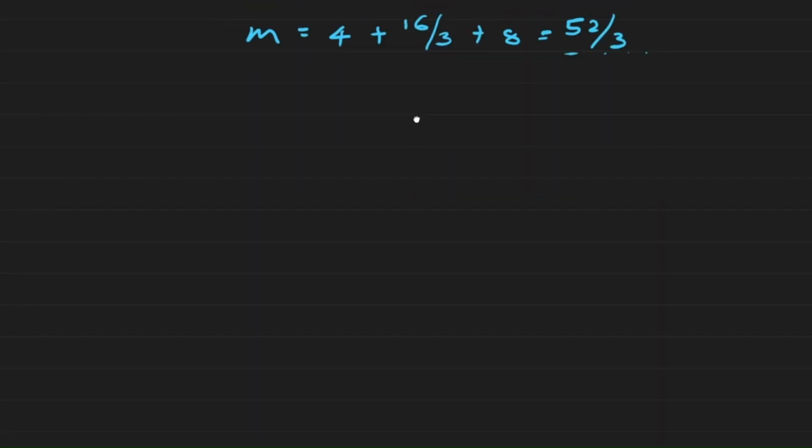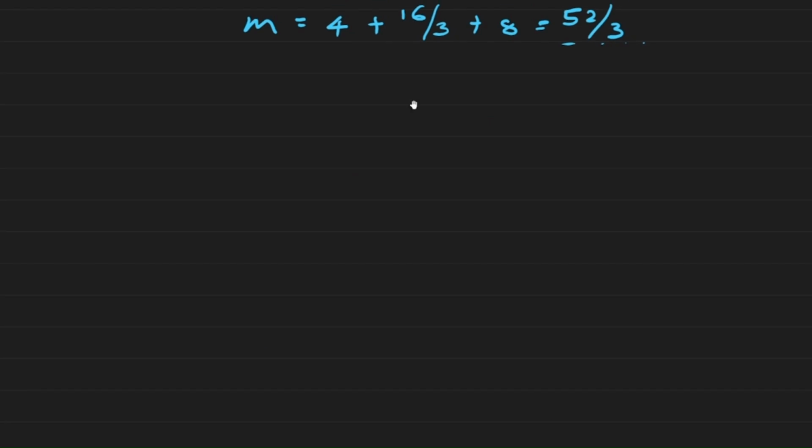We can see that the center of mass, as we had derived it earlier, the x coordinate is simply equal to the sum of the masses multiplied by the x coordinate, which you know now is called the moment, and divided by the total mass, in this case m. So we've determined this mass, and we now need to do the moments. So it's the mass multiplied by the position. So we'll take the moments.